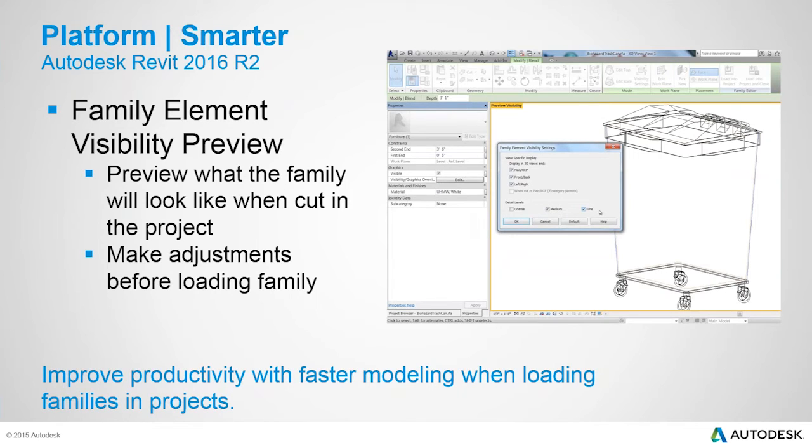Okay, family element visibility. This is a preview feature, and overall you'll find there's quite a lot of new enhancements to the graphics in many areas. The family element visibility preview feature helps you to see your design intent by filtering out geometries that are not viewed. Okay, so when you're actually in and you're editing your family, that is. You can work a lot more quickly because it's just going to be previewing geometries, and you can make adjustments before loading the family